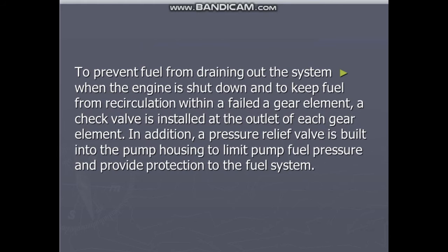To prevent fuel from draining out of the system when the engine is shut down, and to keep fuel from recirculating within a filled gear element, a check valve is installed in or at the outlet of each gear element. In addition, a pressure relief valve is built into the pump housing to limit pump fuel pressure and provide protection to the fuel system.